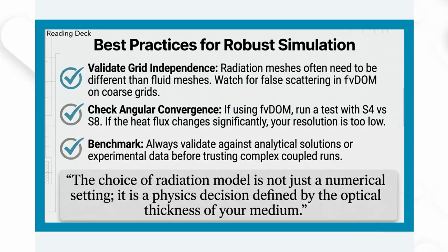And ultimately, the choice of radiation model is really not just a numerical setting. It is a purely physics-based decision, which is defined by your optical thickness and ultimately the cost that you are willing to pay for your simulation itself. But don't just pick the default settings. Look at your fluid. If it is clear, if it is not clear, you let the physics essentially dictate what